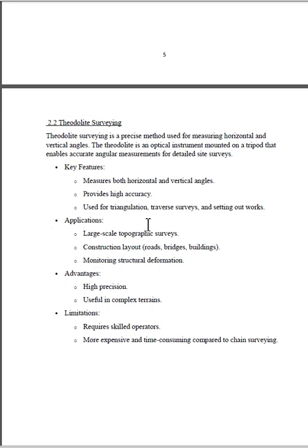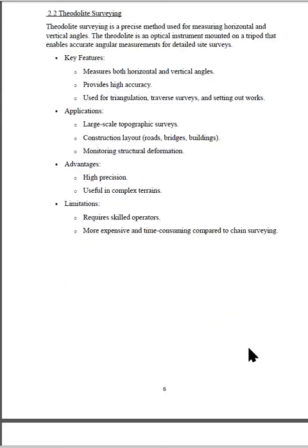Applications: large scale topographic survey, construction layout like roads, bridges, and buildings, monitoring structural deformations. Advantages: high precision, useful in complex terrains. Limitations: requires skilled operators, and is more expensive and time consuming compared to chain survey.